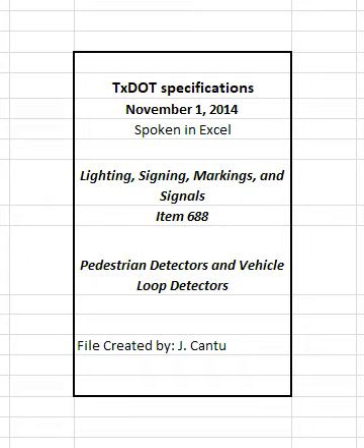Use sealant for the vehicle detector loops in accordance with DMS 6340, Vehicle Loop Wire Sealant. 3. Construction. 3.1 Pedestrian detectors. 3.1.1 Push button unit. Meet the requirements of the TxDOT when installing push buttons. Wire the push button according to manufacturer's installation instructions.